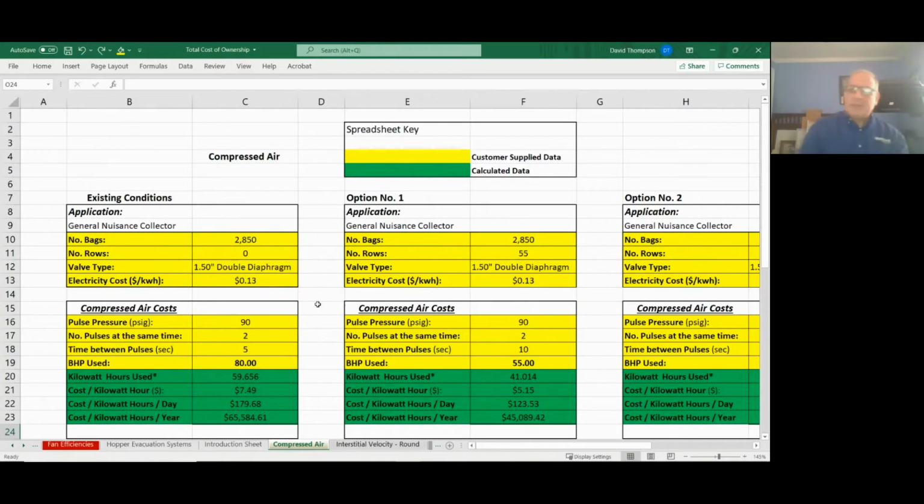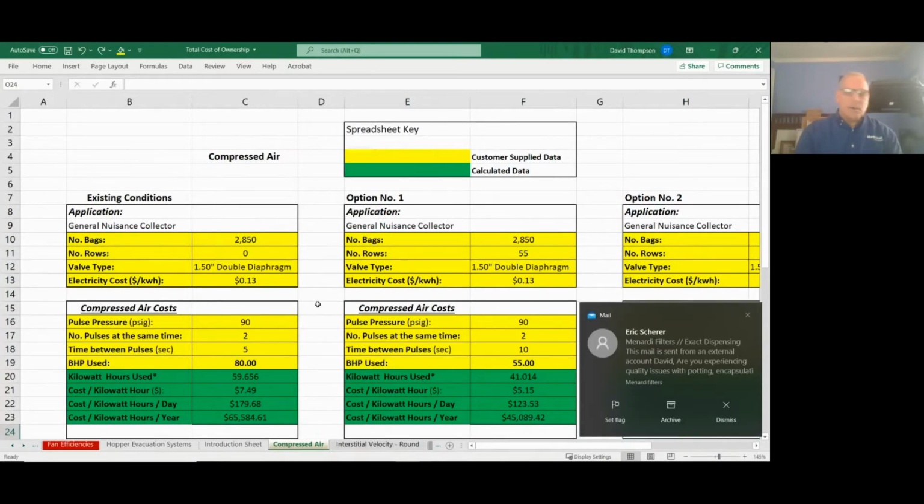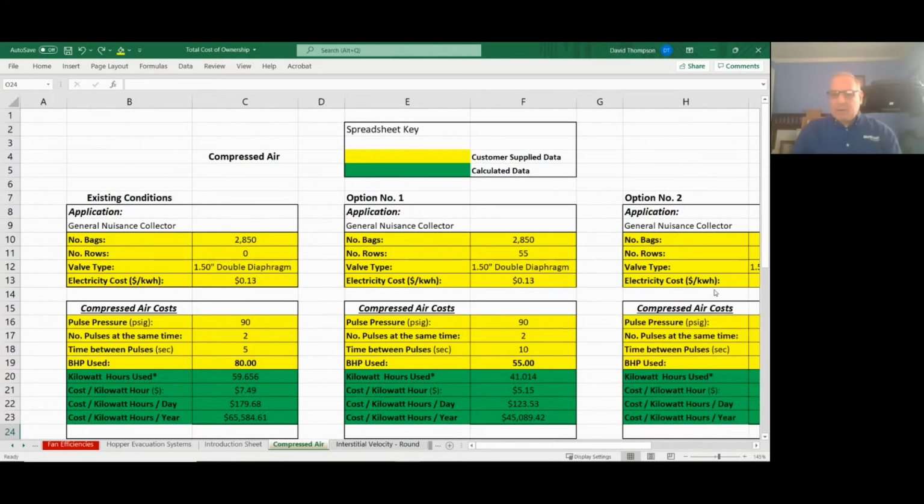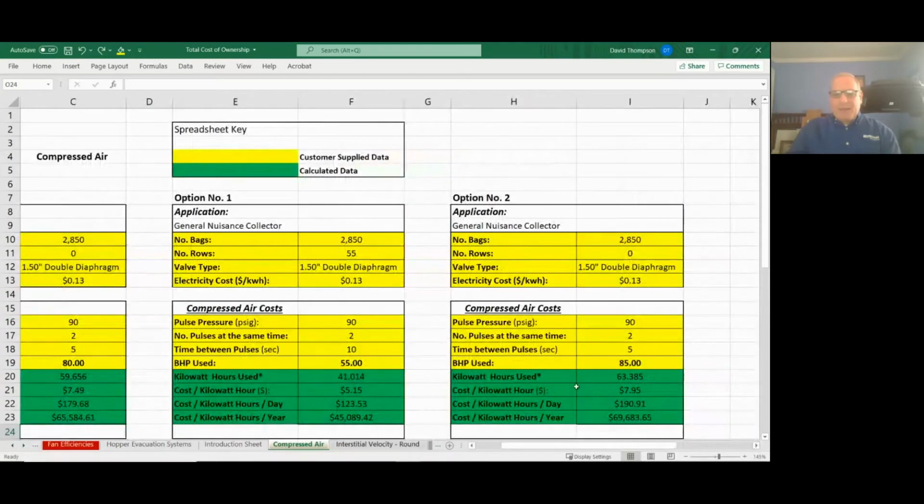And even though there's a slightly higher upfront cost for them, they're much more forgiving, and they allow you to operate right from the start without having to worry about seasoning your bags and making sure they're working properly. So when you turn the switch on a system with a membrane bag, it's ready to run. Because we can run them at higher differential pressures, there's more time in between pulse cycles and cleaning cycles. So that is a cost savings right away.